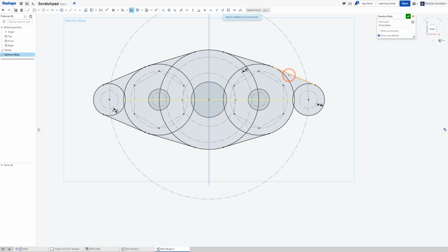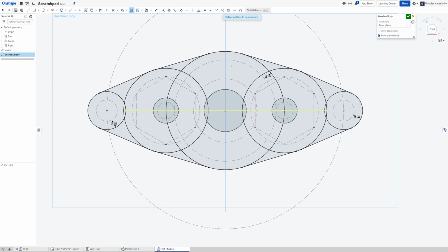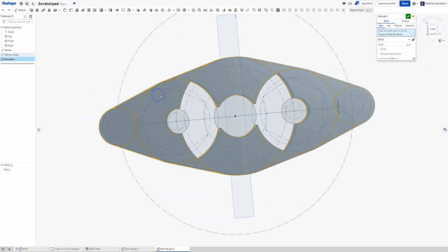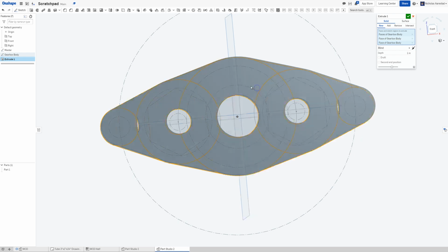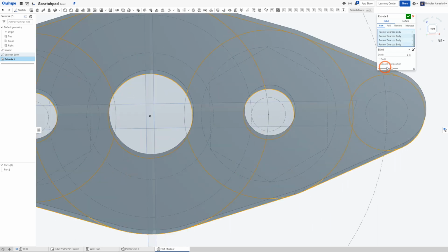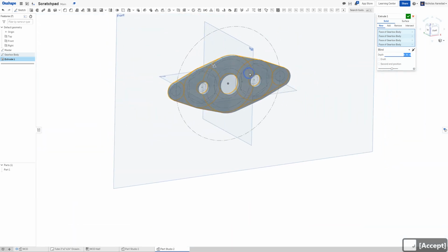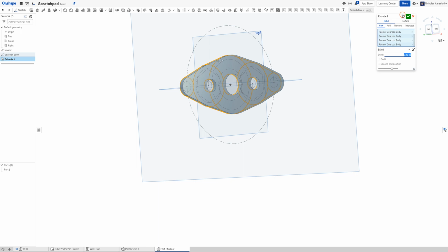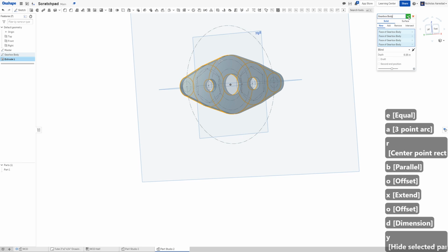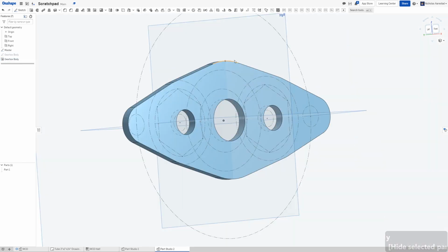And this is why I really emphasize you stick with that center piece. It makes your life easier. Cool. And then this is going to be really nasty. A little bit of a nasty thing. So you have to click these sections that it accidentally grabbed. I'll change this to a 1/4 inch there. One of the things you'll notice I did there is I used Shift E to extrude that, which is nice.